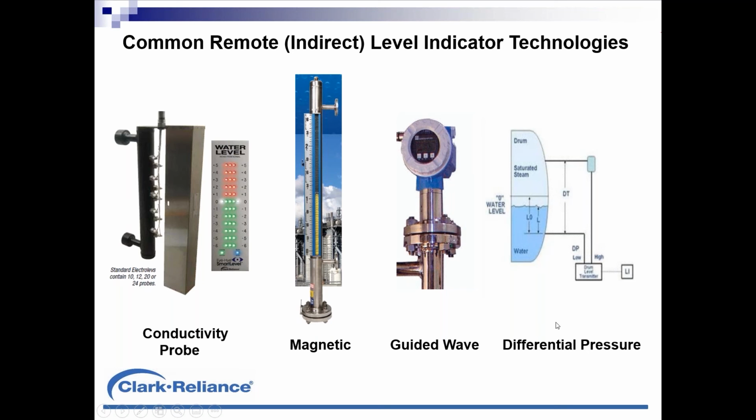And these differential pressure transmitters are not maintenance free. I think people see that there's piping there all the time, but don't realize that some of that small diameter piping going to that level transmitter can suffer sediment buildup in that piping over time if it's not blown out periodically, even if it's done on an annual basis. We have proven errors over the years with DP transmitters when they were compared to conductivity probe devices.